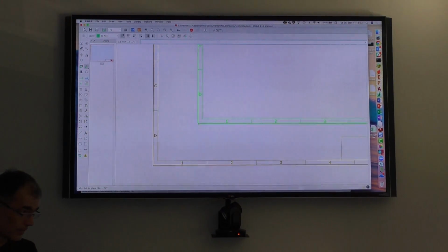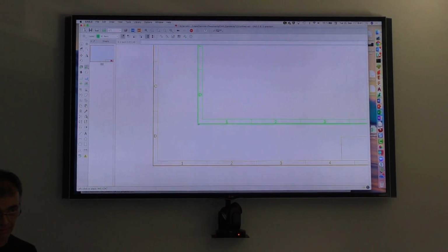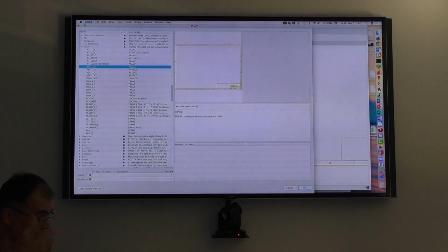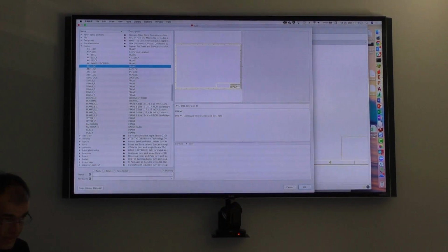If I move the mouse away, the next component is on the mouse. I don't need a frame, but it could happen if you have a resistor, you don't want to place one, but you typically want 2, 3, 4, then you can simply click, click, click. And I don't have to abort or terminate the command. I simply go on and click onto the icon again. Then I come back into my dialog and I can place the next one. So save mouse clicks. That's save, take care of the environment, save mouse clicks.